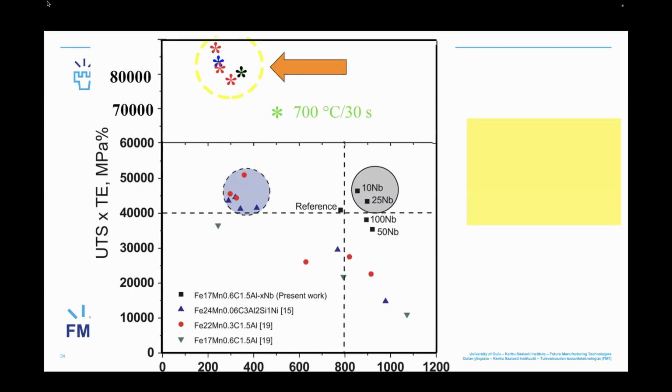So now this material, the steel including niobium, you can also see from this one. So we suggest that if we have this without any microalloying element, vanadium or niobium, and you add niobium or vanadium, the yield strength would shift very high, would be like here. So it can be much better than other materials. This technique is promising for steel processing in industry.